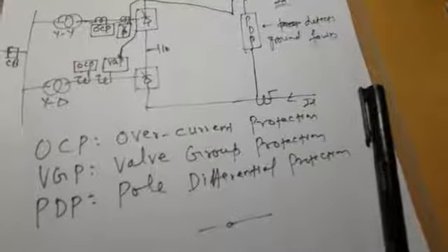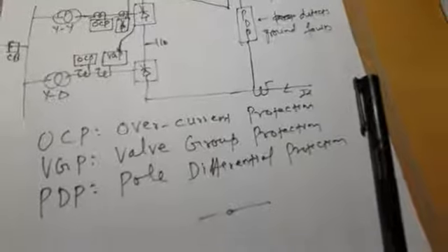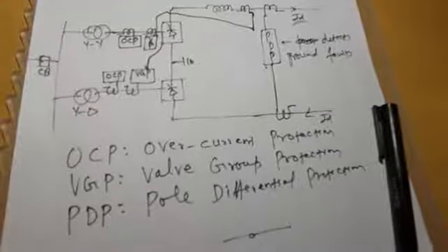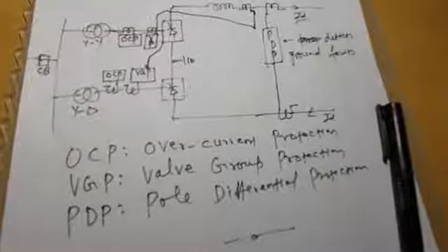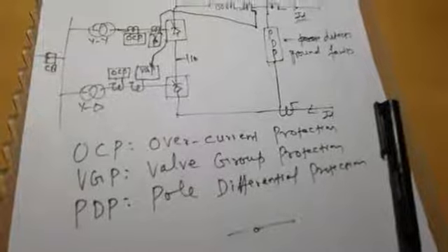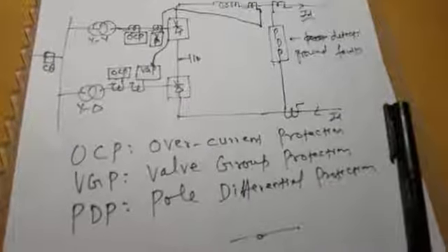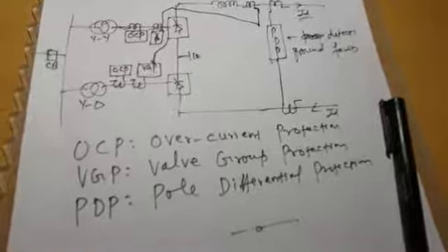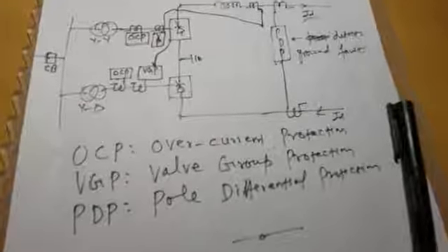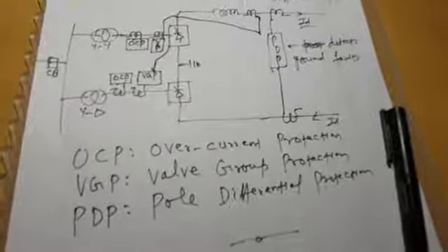That will cause overvoltage. And then maloperations like misfire, arc through, or commutation failure cause certain voltage jumps, and in presence of inductances and capacitances these cause current and voltage oscillations, and they result in overvoltages. That means these maloperations are also responsible for converter station overvoltages.